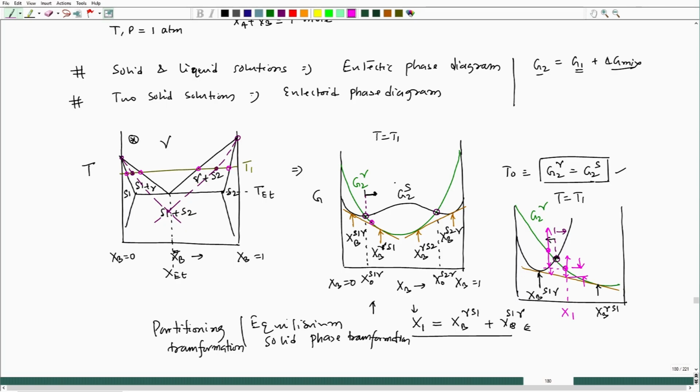So, that means if the system finds that there is no more change required, only the crystal structure change, the system would try to follow that, because for that we need less activation energy. So, this is part of the phase transformation kinetics that needs less activation energy.